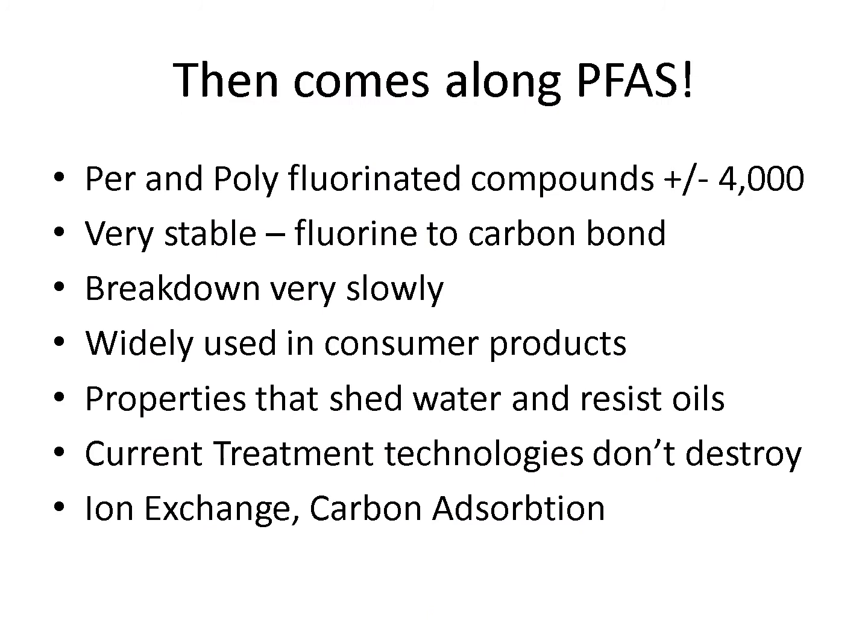And then you have PFAS. This is an absolutely huge issue for wastewater treatment facilities, and at the present time there are not a lot of good, quote-unquote, solutions to PFAS. So what are they? PFAS are per- and polyfluorinated compounds. I've been told there are greater than 4,000 different compounds that fall into the category of PFAS.